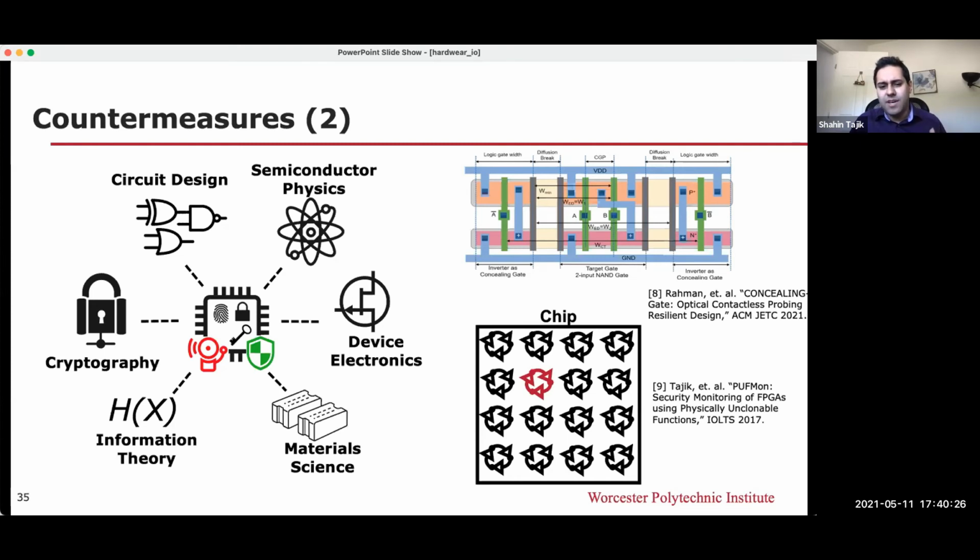By the way, this kind of analysis that I showed you is usually done by a laser beam which has a longer wavelength than that usually used by laser fault injection, so there is no photoelectric effect on the chip. It means that even if you have a light sensor, it's not going to trigger when the laser hits. The laser only heats up the transistors on the chip, the silicon. So you need circuitry which is sensitive to local temperature increases.